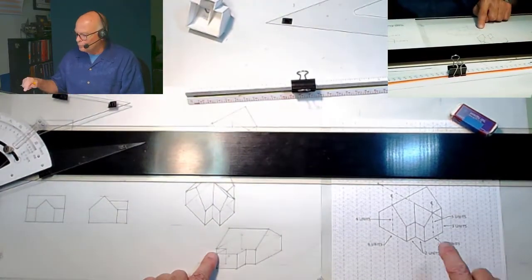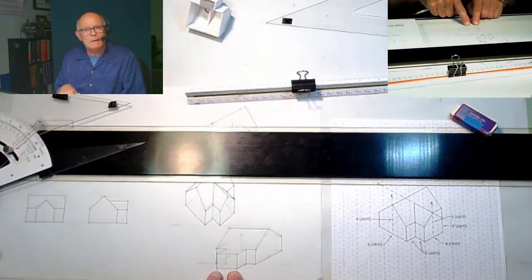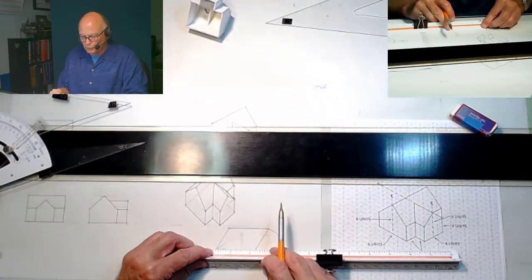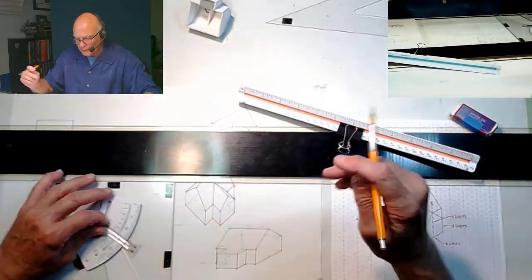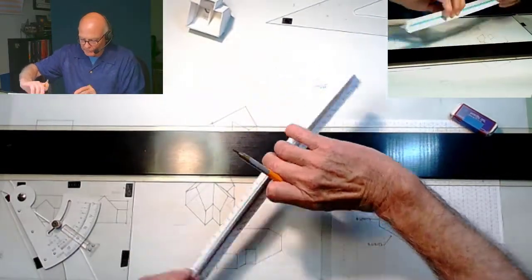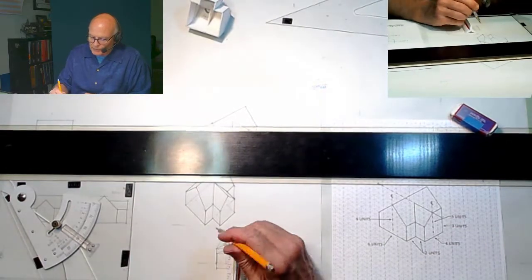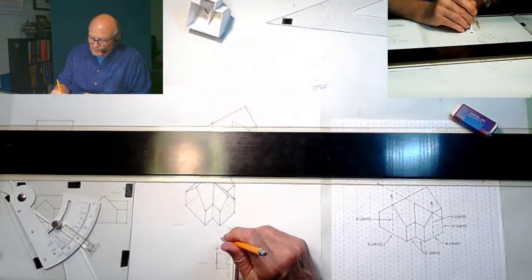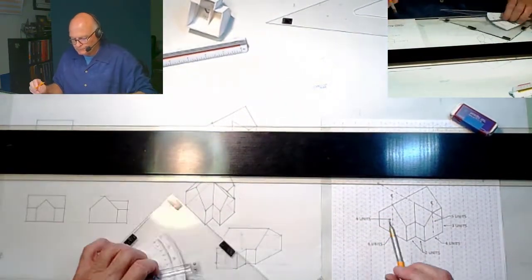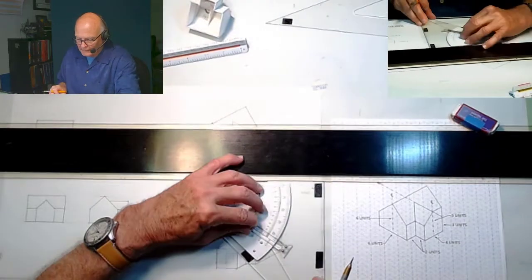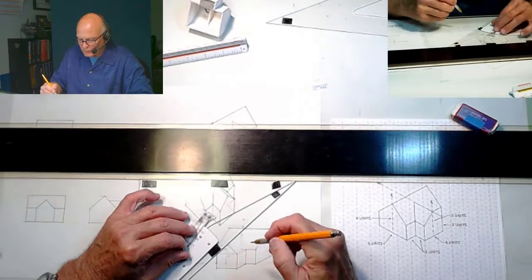So as we did before, as we did with the isometric and the plan oblique, we're going to go to the middle, which is 4. We're going to go 2 over, and we're going to project upward, and we're going to go up 5. So we get our scale. We're going to go 5 units up. And we mark it. Now, again, this should be on a 45, similar to what we looked at before.